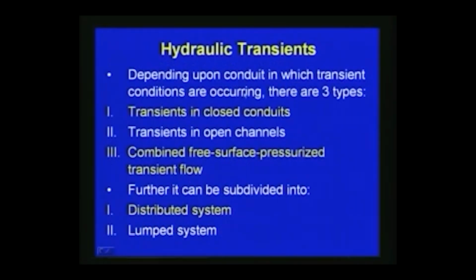Now, as I mentioned, in the case of a sudden valve closure, a wave is generated, the water hammer velocity is happening, and the wave goes back and again comes back. So, there will be a translatory movement between the valve closed and the reservoir, and then periodically wave action takes place. We have seen the velocity of the water hammer, and we have derived a relationship.